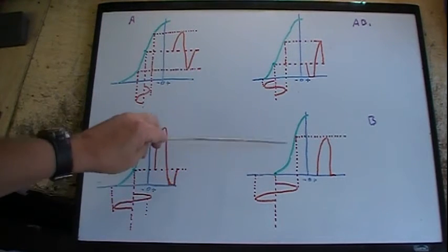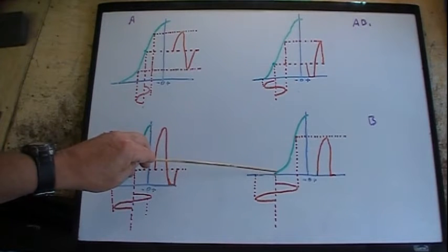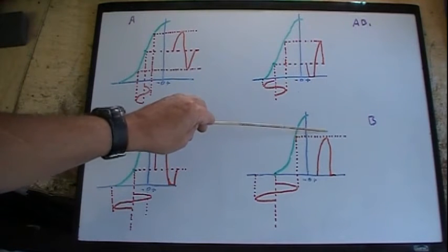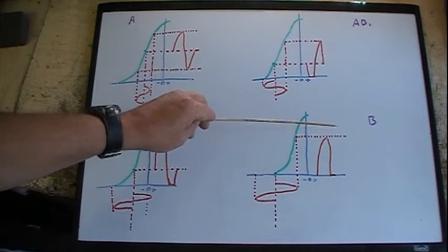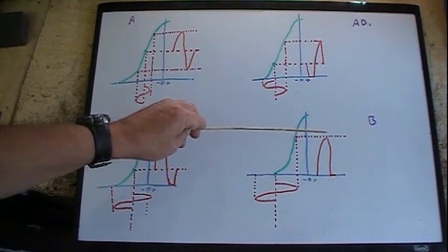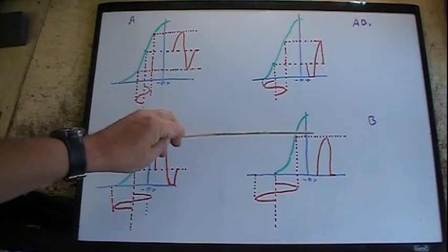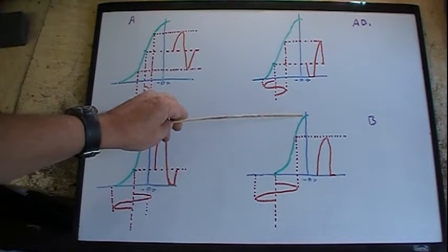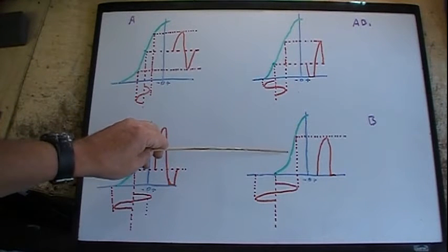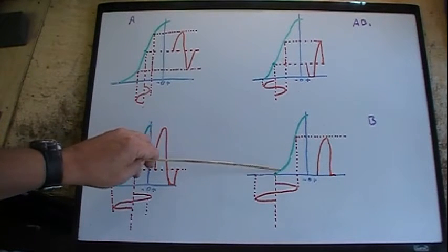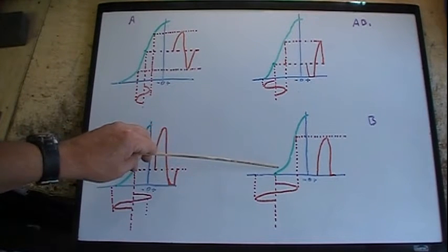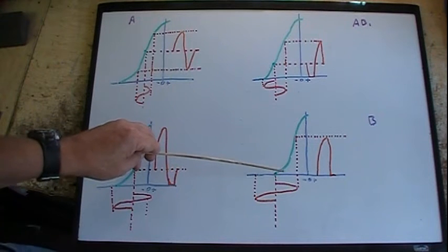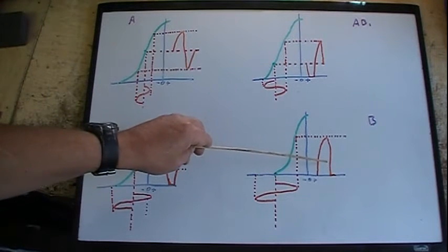The thing is, since it's so far down the curve, right down at the bottom here, we can actually get the greatest amount of gain, amplification. So Class B will put out the most power of any of the other classes. But not only is it operating along the linear path, it's also operating in this knee right down in here, which is a pretty good curve, and that produces a considerable amount of distortion. So it distorts the worst.